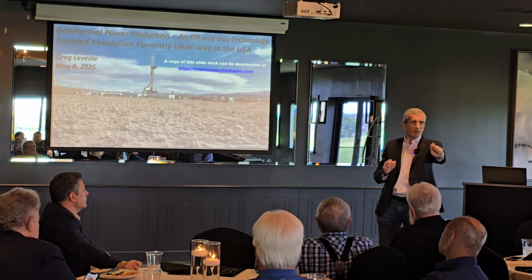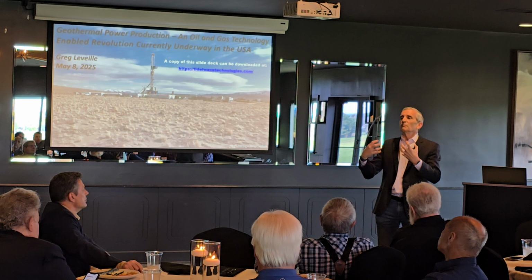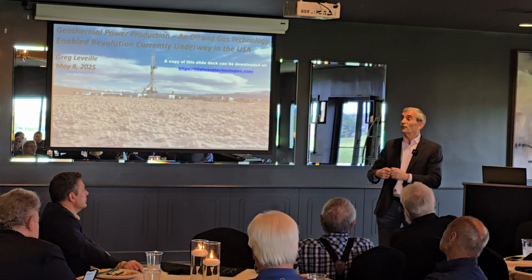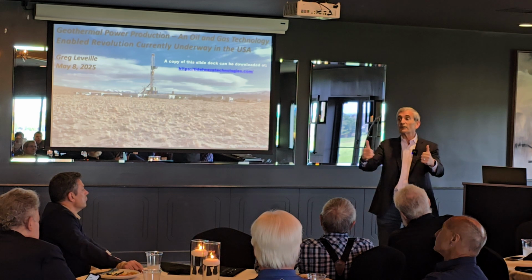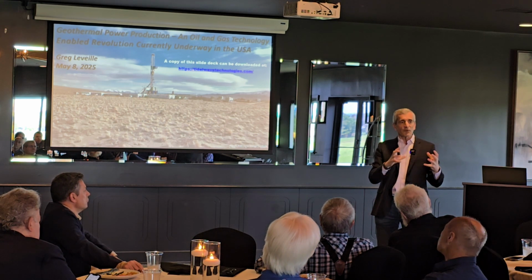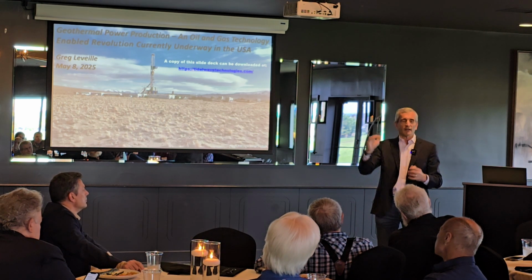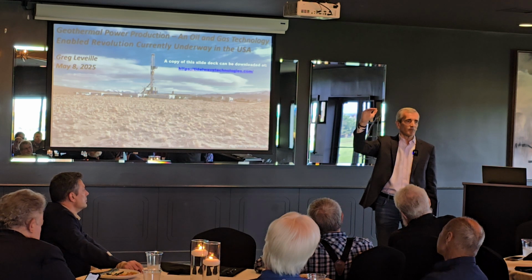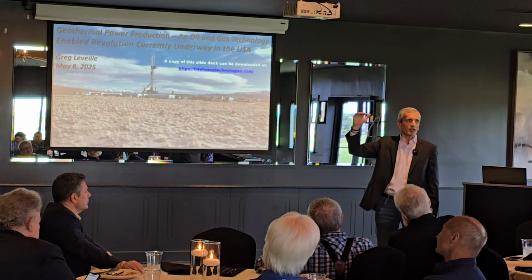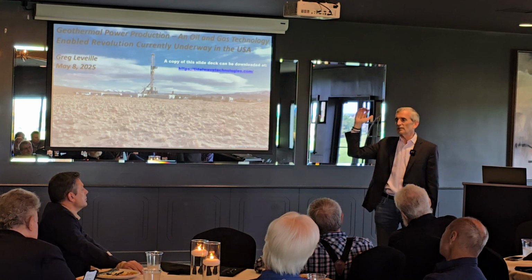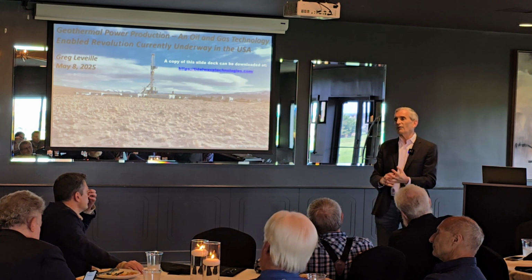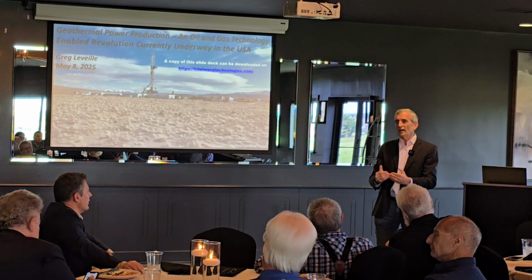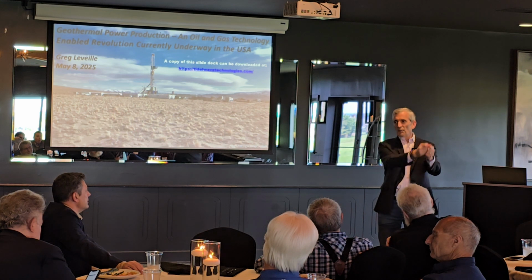The rest of it is at reservoir temperature. So how far apart the wells are matters; if you drill a longer lateral and slow down the rate at which the water's moving through the fractures, that helps. So there's a lot of different engineering issues here. I've hit this at a really high, simple level, but there's tons of work here for reservoir engineers, completion engineers, anyone who wants to think about essentially that topic, Scott: how do I maximize the time before that cold water shows up in my producer?